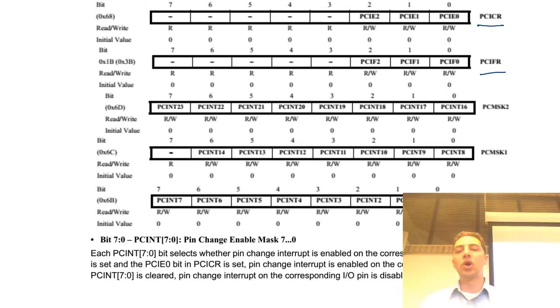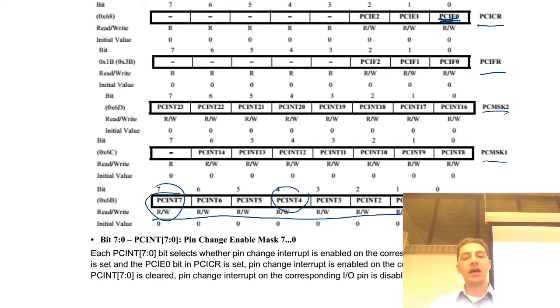But there's even more masking going on here, because each of these 7 or 8 bits in each of these registers corresponds to a particular physical pin on the device. And it's grouped up. So if you enable this group, you further have to say which pins will activate. You could set that pin high and that pin high, and then you would have 2 pins that would trigger the same interrupt.